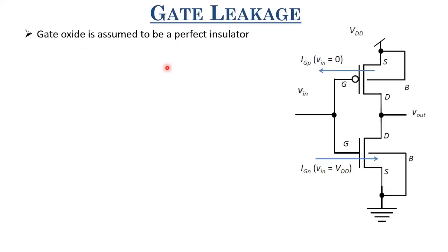So what is field effect? Whatever voltage you are applying here, how much of that is being coupled to the channel? Because that decides how efficiently you are controlling the channel electrostatics, how efficiently you are able to invert the channel, how efficiently you are able to put the channel in depletion, and so on. That depends upon the electric field between the metal and the semiconductor, and your insulator is what couples that electric field. So a thinner insulator will give you a higher capacitance and couple electric fields in an efficient way. That is the reason for going to ultra thin gate oxides.